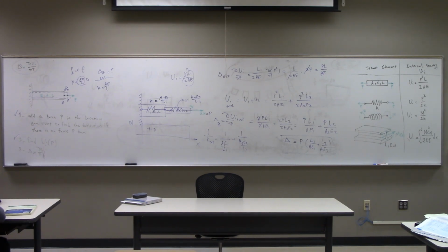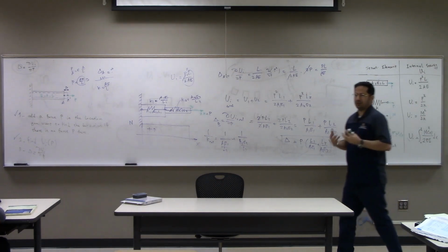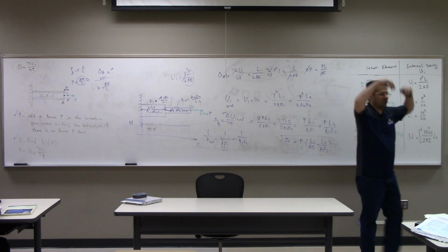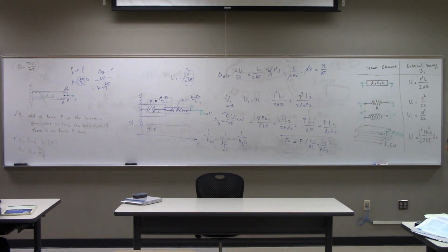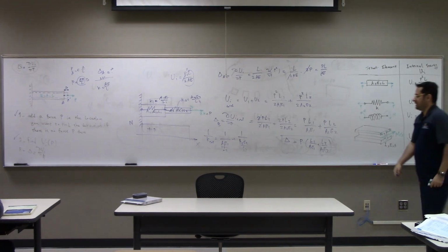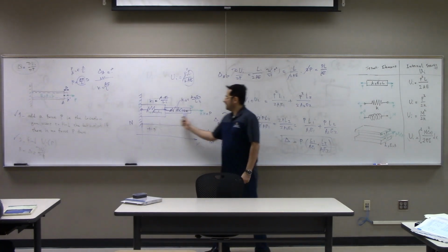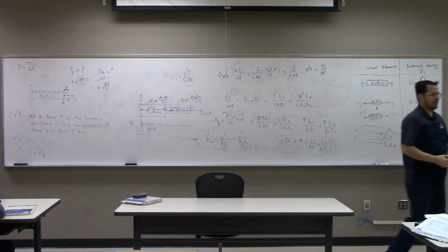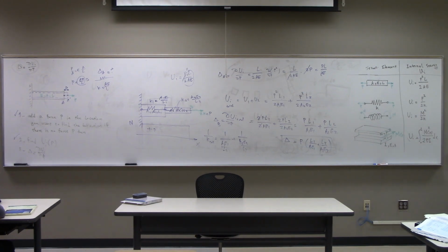So the way you do it, you convert everything to pins, right? That means that you use your intuition. You don't just close your eyes, write the energy function for the entire structure, and take the derivative. You just simplify. And then you say, well, for the deflection here, maybe the spring method is your next guess. I combine this element into like 3, 4 springs, and then I simplify the deflection.